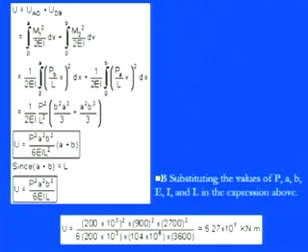By simply adding that part and taking out A square B square, we have the strain energy within that component, U, as P square A square B square divided by 6 times EI L square into A plus B. A plus B is nothing but the total length of the beam, L. So replacing that, the final strain energy under the bending action, where the simple point load is at a distance A from the left end, is U equals P square A square B square divided by 6 EI into L.